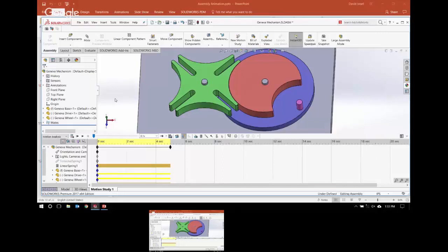They're just considered to be rigid bodies. If you got into the full motion analysis, you can get results from a study like that which would show reaction forces, and then you could import that into a simulation study, and you could see deformations from that amount of force.